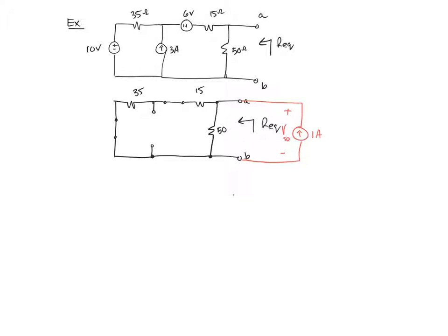Note the polarity that I assigned, the positive on the top, negative on the bottom with the current going up, and that's because this is the only independent source I have in the problem. This must be supplying power. So I just know that that's the case.